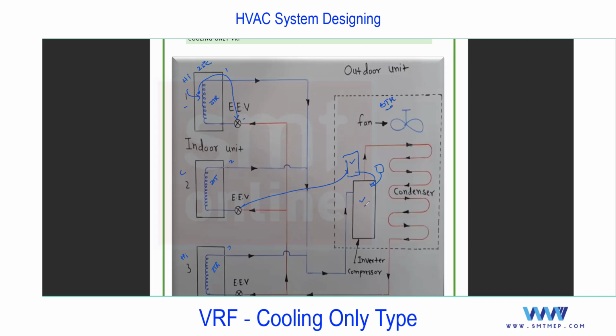And reducing the compressor speed will reduce the flow, or the volume, of refrigerant. So we call this system VRF or VRV. And the same thing happens as per the load demand inside the spaces or inside the building. Very simple concept. But this can be achieved precisely only with the control units. Within seconds, the compressor must reduce the speed, or else if the pressure in the line increases, what will happen? The system may fail, with leakages. So this is a precise type of system.